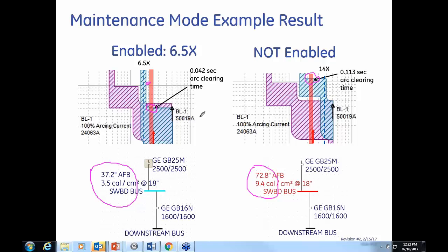than what you've entered in the software, you could end up with an arcing current that is in fact lower than predicted. And the effect of that would be, if this rose-colored band were actually further to the left, you might end up with a clearing time that is in fact much larger than what you're bargaining for. Okay? So then if I want more margin of safety than what I'm showing here,